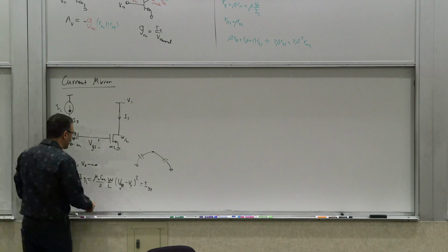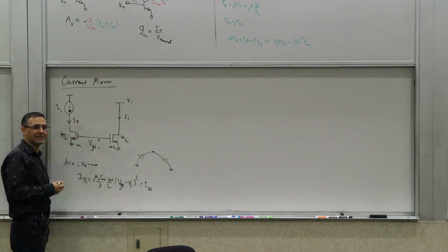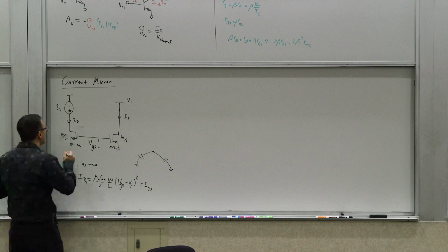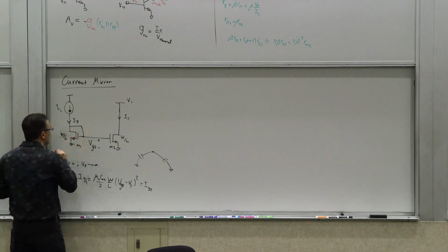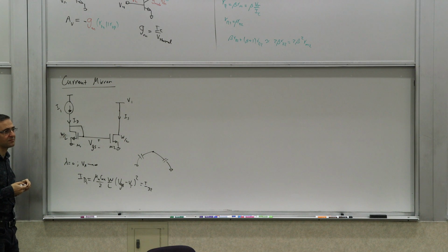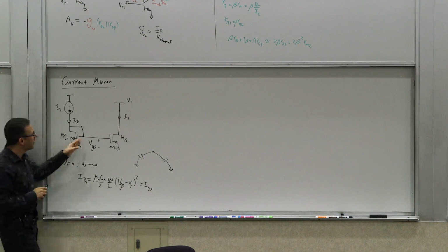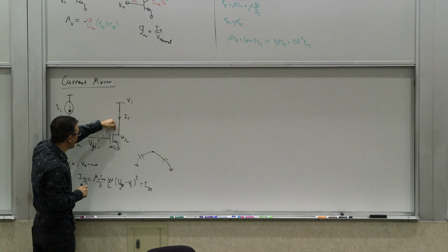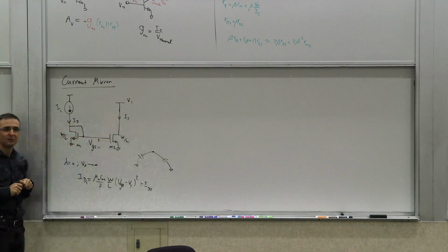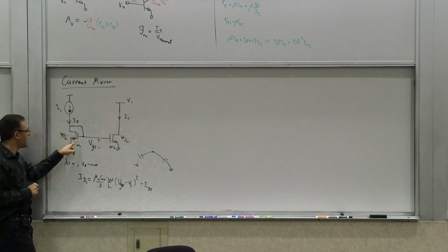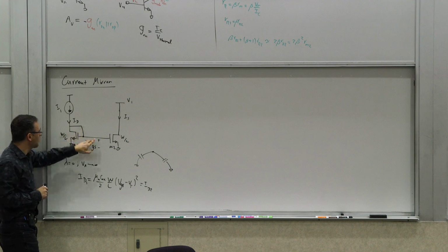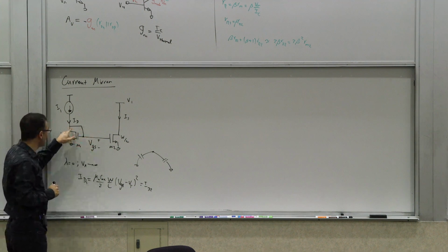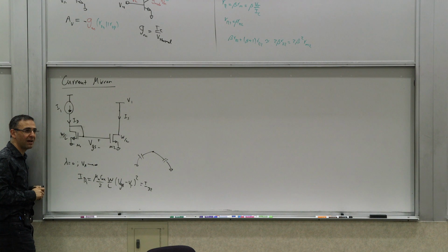Right? So there needs to be some connection to this gate. Now, we do it by doing this. We connect it to this side, which is the reference side, and that way we keep the drain of this guy separated from its gate, so we maintain a high impedance here. But by doing so, we create a pathway for charging and discharging of this node, so you keep these two on the same level.